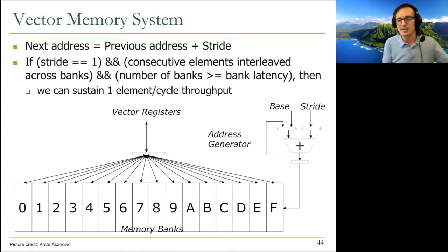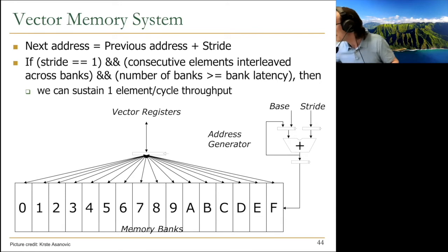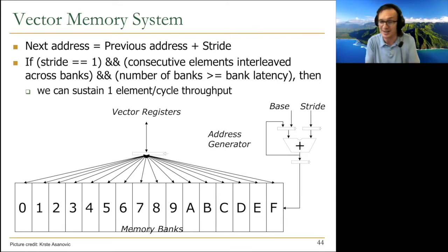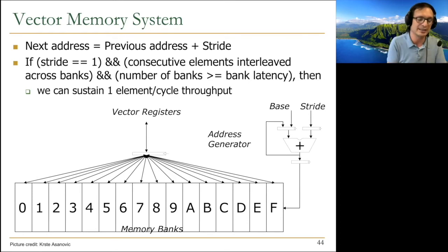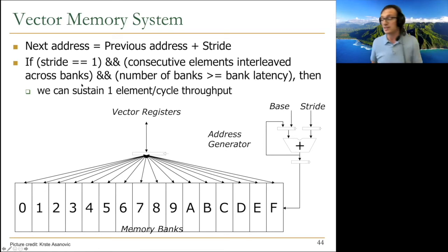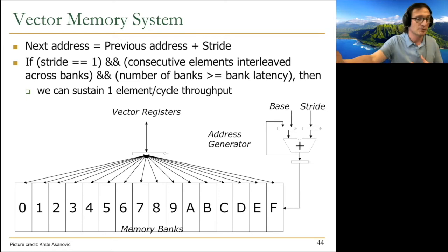Addressing an odd or a non-power of 2 location in memory or bank number is not easy, because we're going to use the address to determine which bank to go to. Some bits in the address will be used to essentially decide which bank that address maps to, right? The bottom bits after the word, in our case, because consecutive elements are interleaved consecutively. But basically, 33 is difficult to build. That's why we go to the next power of 2, which is 64, right? Okay, so very good answers.